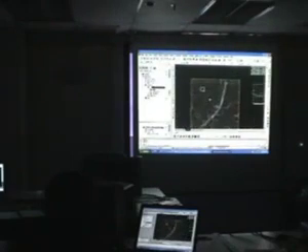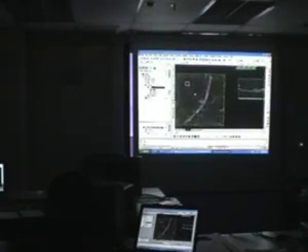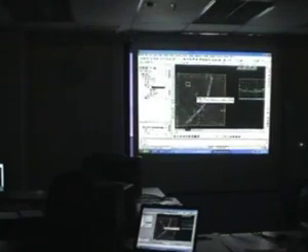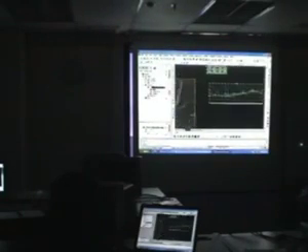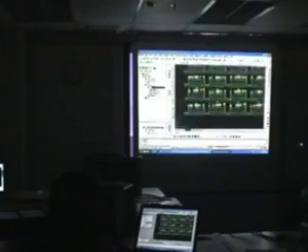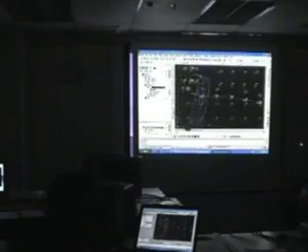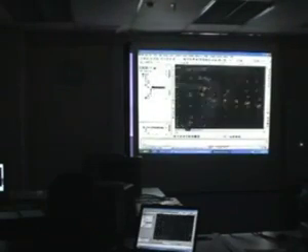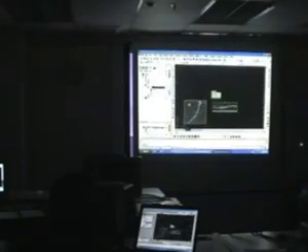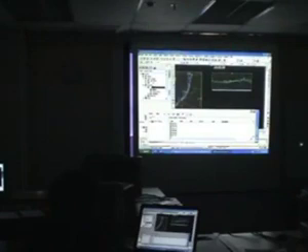Now coming back to the object, what we call the dynamic abilities of Civil 3D. I have already created a road here. We've got a horizontal profile and a vertical profile. We've even got some cross sections in here. So I'm just going to click here and get hold of my horizontal alignment. I want you to look at the vertical. You can see the vertical has been adjusted automatically.